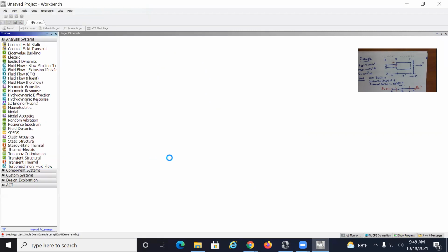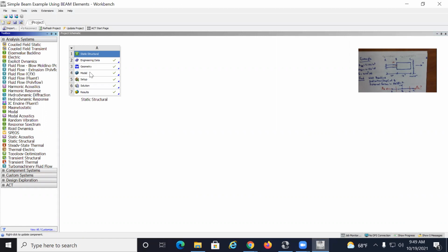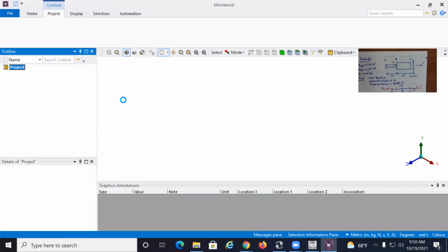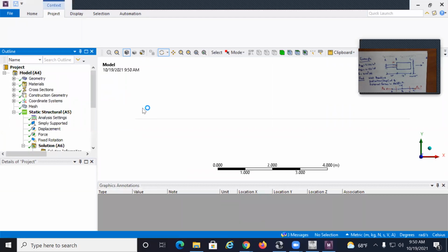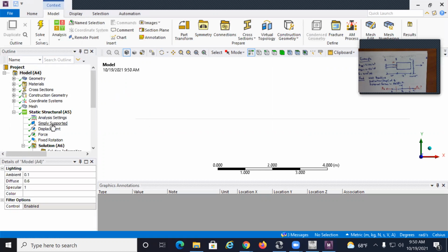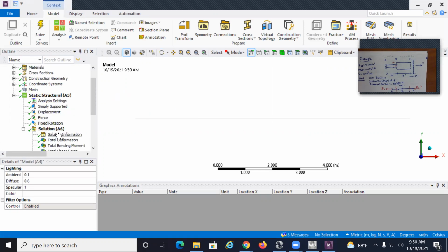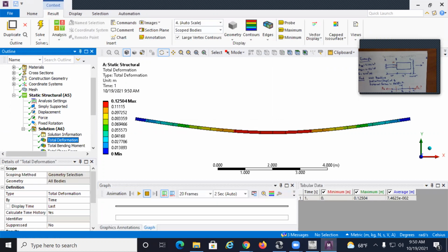So I'm going to open here one of the beam problems that we've done and remind you where to look for axial stress. Now, when we say axial stress, it is referring to the normal stress. So the stress along the axis of the member is the normal stress, sigma x, correct? So when I look at this simply supported beam, this is the example we did in class.